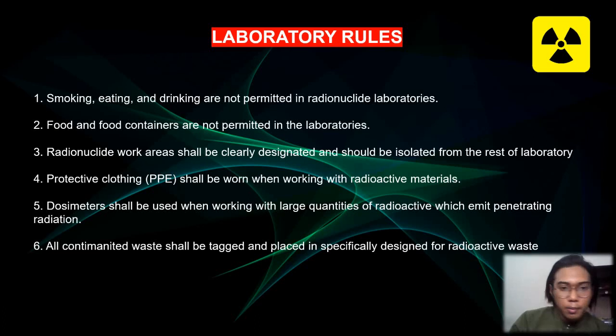Fourth, PPE should be worn. And fifth, a dosimeter should also be used when working with large quantities of radioactive material. And lastly, all contaminated waste shall be tagged and placed in containers specifically designated for radioactive waste. Later, I will explain how to dispose of the radioactive waste.